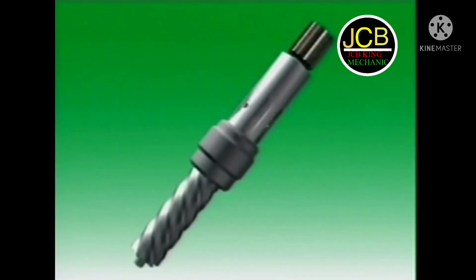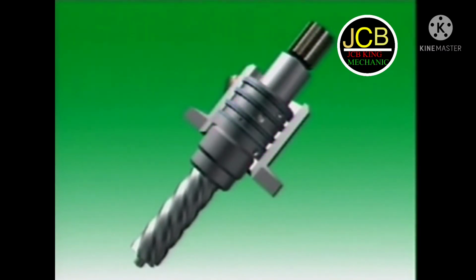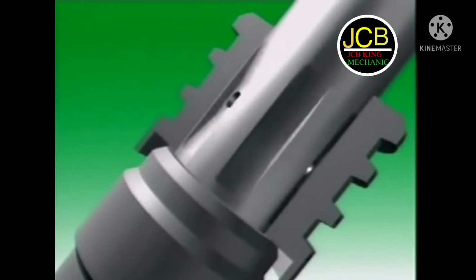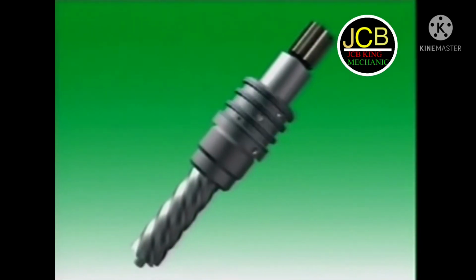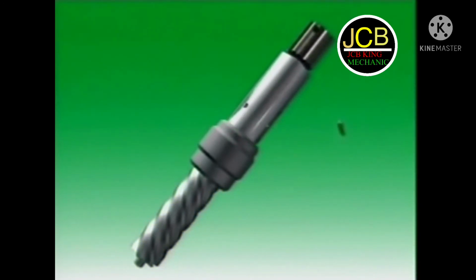It consists of an inner member which forms part of the input shaft and a surrounding sleeve member fixed to the pinion gear. Turning the steering wheels makes both members rotate in the steering gear housing, but it is the slight relative rotary displacement of the inner member and the sleeve member which controls and directs the power steering fluid flow. This slight rotary displacement is allowed by a torsion bar, which is connected to the pinion gear at its bottom end and the input shaft at its top end.